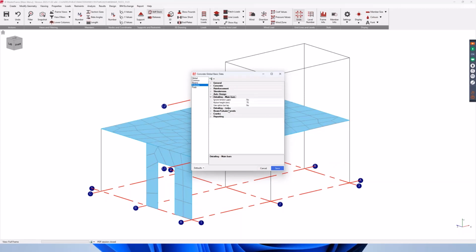So for example, in columns where column dimensions are different for each lift, the program can use splice bars instead of crank bars. For example, we can use single leg internal link, or in circular columns we can use hoops instead of a helix.